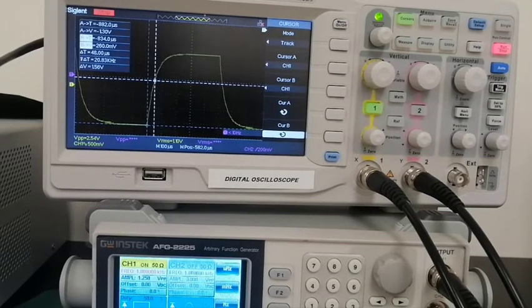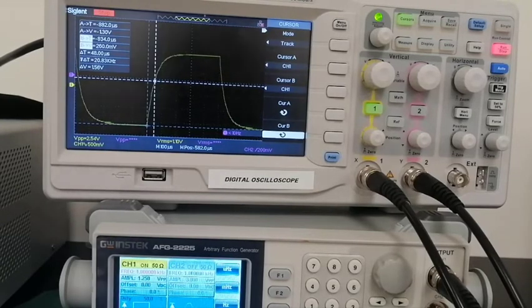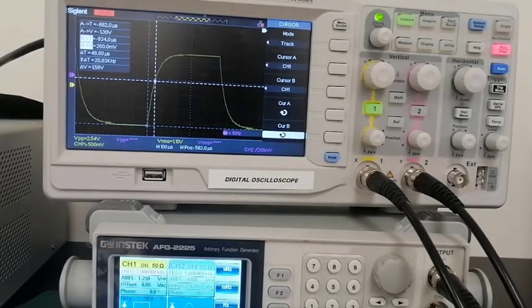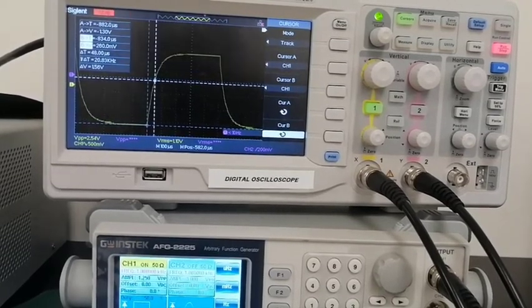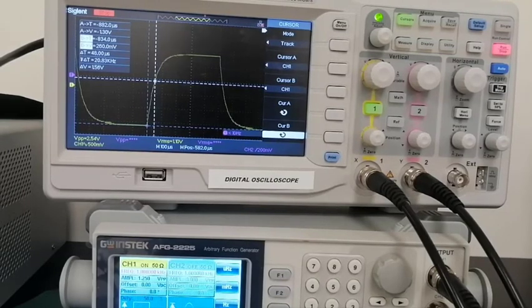So we can take the measurement for the rest of the table. For the first time constant, the voltage across the capacitor is shown as 63%, confirming the formula that the first time constant should be 63%. When I was designing the circuit, it also showed 63%.